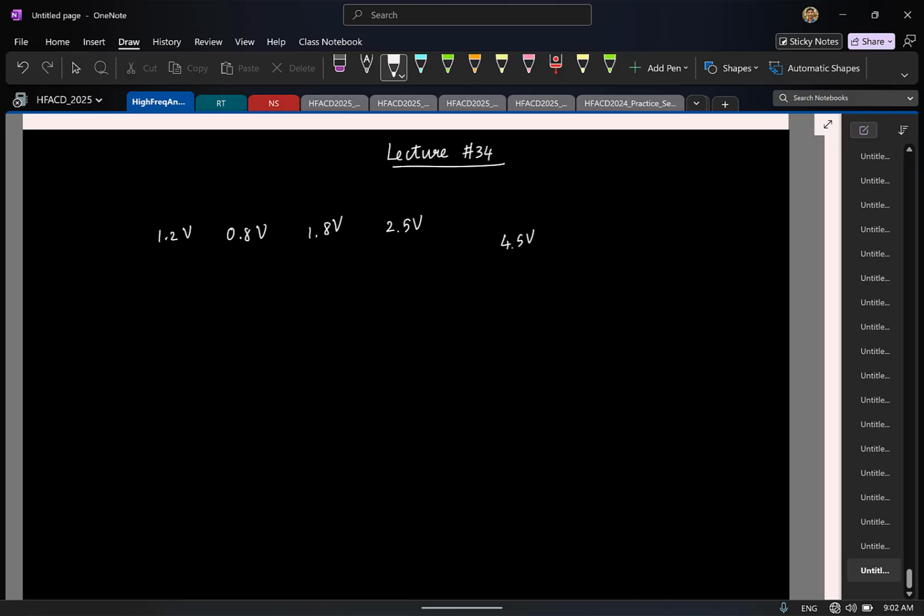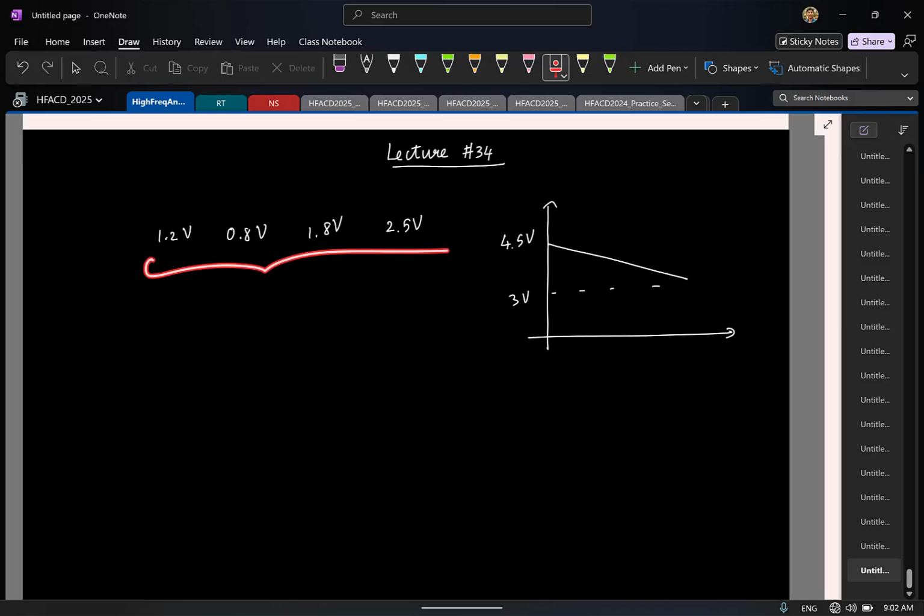But of course, the battery is not fully charged. It starts discharging. Of course, if you let it stand by, it will discharge slower. But if you keep watching Instagram reels throughout the day, it will discharge faster. And it turns out once it discharges fully, the voltage is about 3 volts or something. Now it turns out all your circuits, that is all the chips that are manufactured, will be designed so that even if the power supply varies by, let us say, plus or minus 10%, the functionality is fine. Beyond that, you can't guarantee.